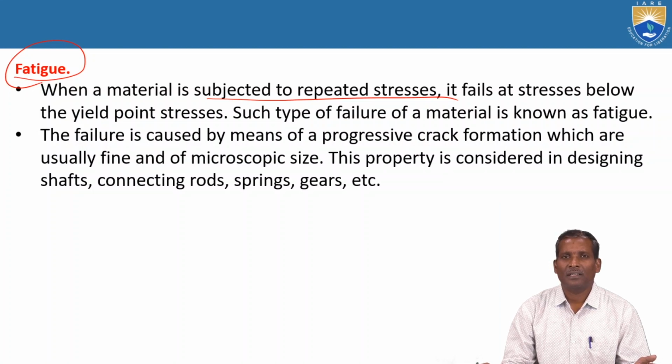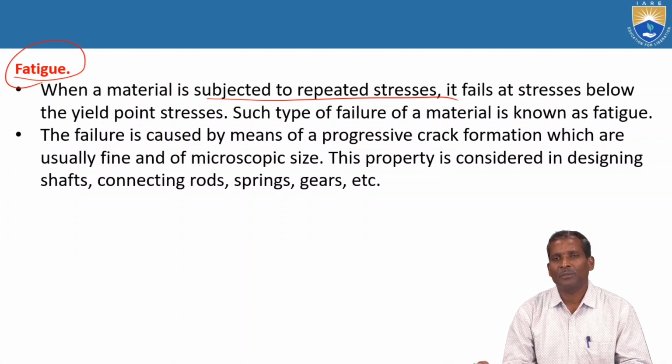So how to calculate this fatigue? By using an S-N curve, and you can conduct experiments on a rotating beam fatigue tester. Whenever the component is subjected to repeated stresses, meaning variable stress or cyclic loads, then the fatigue property will occur in the component.